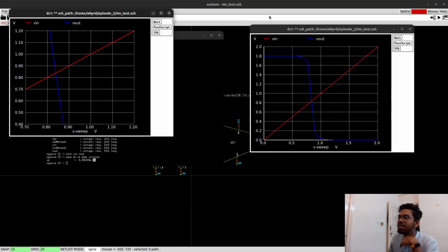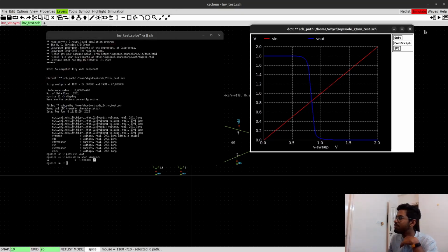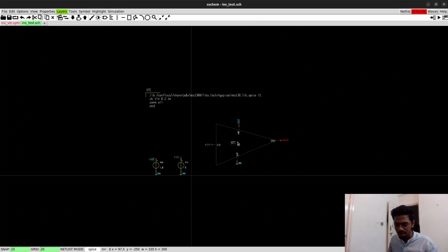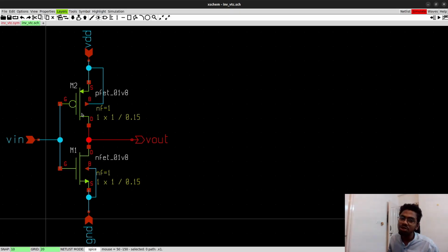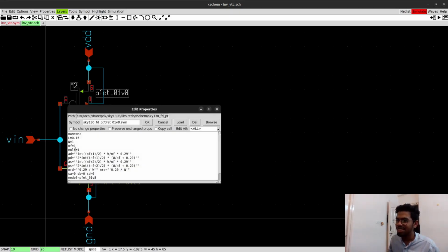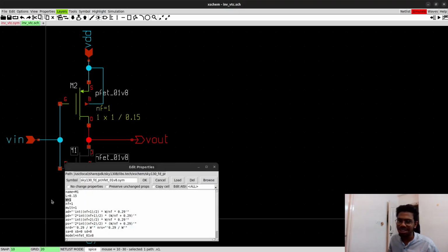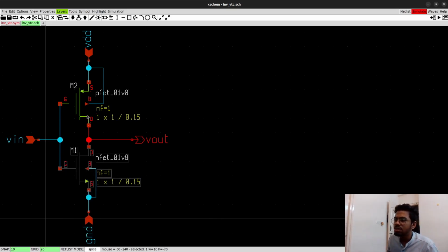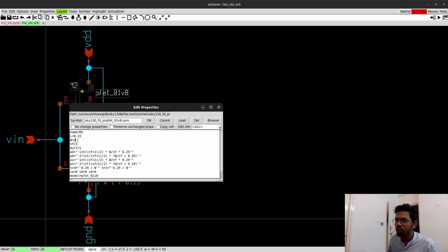And the fundamental thing we are missing here, I have done wrong, let me go inside. What's the width of your PMOS? It is 1. And what's the width of your NMOS? It is 1. It should be minimum, W by L of PMOS by NMOS should be 2. Best is 3+, but we don't go there because of area penalty. So it should be 2, and that's the mistake I have done. So let me make it 2, and we'll see again how our VTC is working.